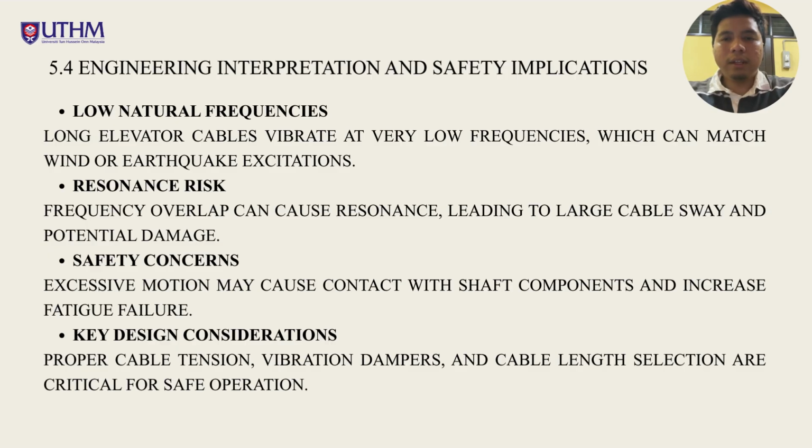This resonance can lead to excessive cable sway, which increases the risk of contact with shaft components and accelerates fatigue damage. Therefore, from an engineering and safety perspective, it is essential to manage cable tension properly, use vibration dampers, and carefully consider cable length during elevator design. Even with a simplified model, these insights are valuable for ensuring safe and reliable elevator operation.